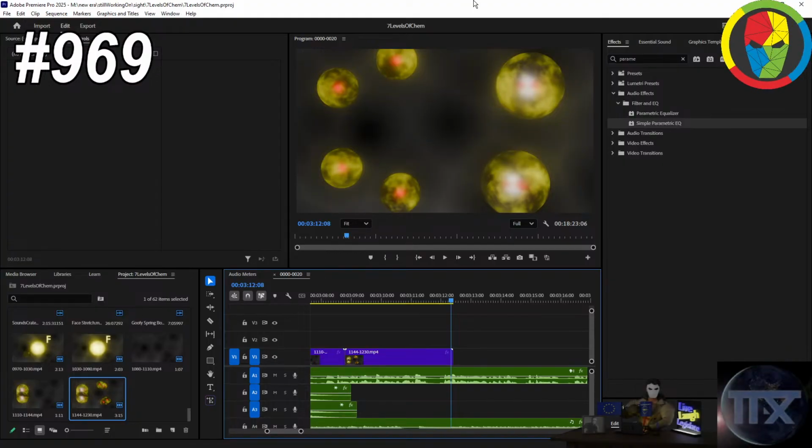See, I listen. But I'm going to have a main data line, and the data line will go to Raspberry Pi Picos onto the I2C one, and then whenever I connect everything to power, I'm going to have the master device, which will be the Raspberry Pi 5, send out a signal on I2C, asking every single device on that network what it is, and that way I'll be able to dynamically hook up the addresses. And on the other networks, it won't really matter because they'll be extremely static. Nothing will change in them. So hopefully the addresses will be constant. Yeah. It's never good when you have to say hopefully something will be constant in electronics, but hey, that's where I am at right now.